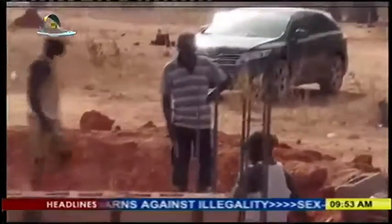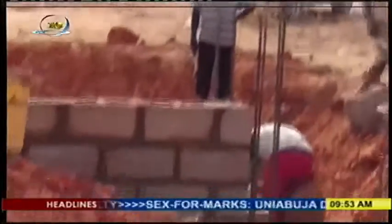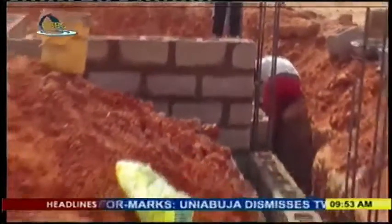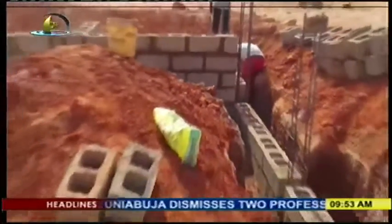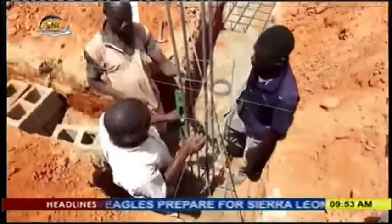You can clearly see the columns, and you can see the reinforcing steel sticking up. If you look closely, there are ties that are used to hold those vertical bars, right? There's a quick thing on columns. When you load a column, part of the load goes into the concrete itself. The other part of it goes into those reinforcing bars.